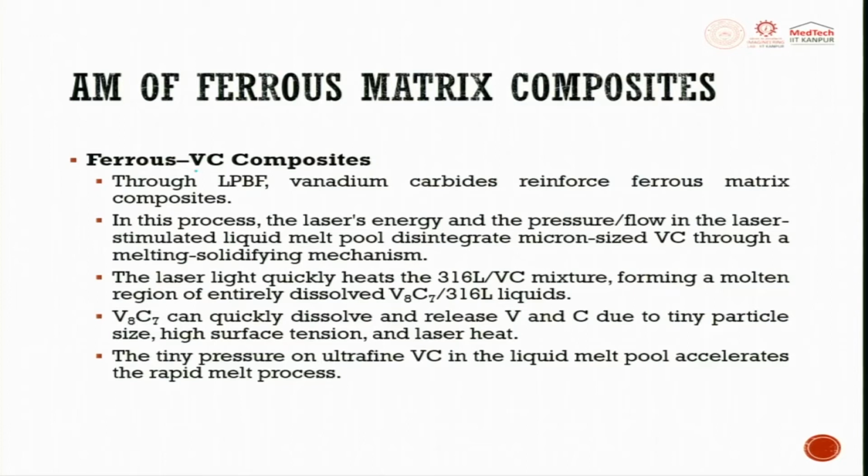We can also have vanadium carbide. Through laser powder bed fusion, a vanadium carbide reinforced ferrous matrix composite is also considered. In this process, the laser energy and the pressure in the laser stimulated liquid metal pool disintegrate micron size vanadium carbide through a melting solidifying mechanism.